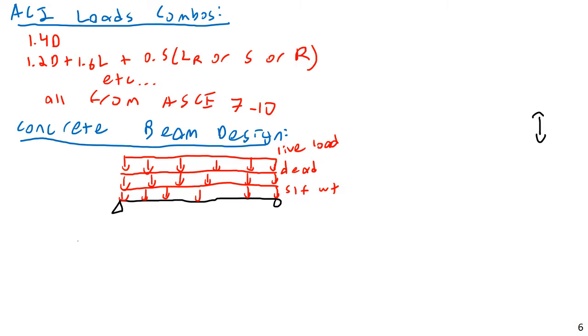Now, in mechanics of materials, when we learn how to do beam design, you do both of those simultaneously. And in statics, of course, you're just calculating the shear and moment that must be resisted. You're not actually calculating the stresses involved and what kind of sections are required, etc. But for the way concrete works, for the typical loads we carry, bending tends to be more critical than shear. It's very rare for a section's design to be controlled by shear.